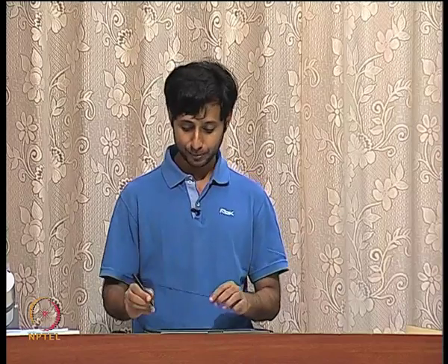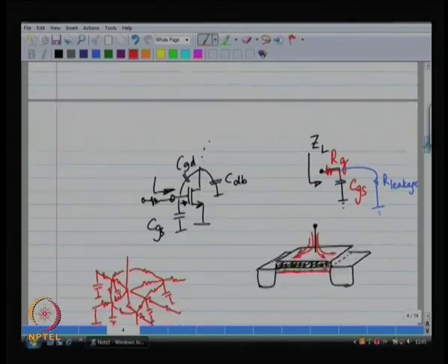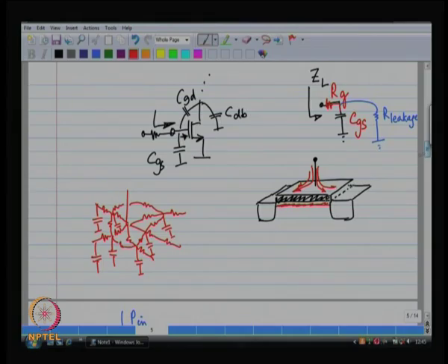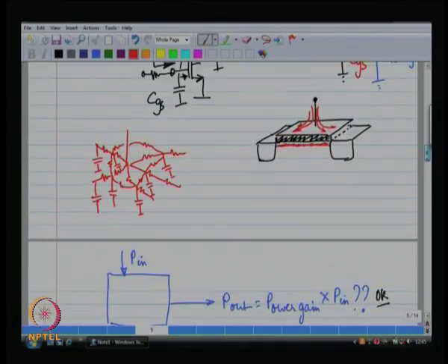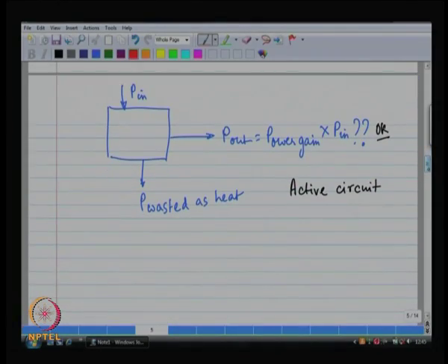Okay. All right. So, this is the situation that we had for the LNA. If I manage to do maximum power transfer, I do not get any reflections. I also get the maximum output power because my amplifier has a finite power gain. Then we talked about what is this power gain we are talking about, because the input of the amplifier is capacitive primarily. There is also a small resistive component as far as the gate is concerned. Most of this power is coming from the power supply.